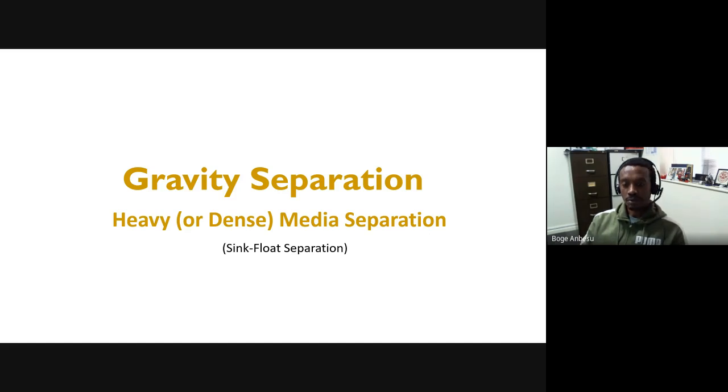And this week we're going to talk about those that use a dense media. So something denser than water typically can be used in gravity concentration. So today we'll focus more on how we can apply dense media separation in mineral processing or in ore beneficiation.